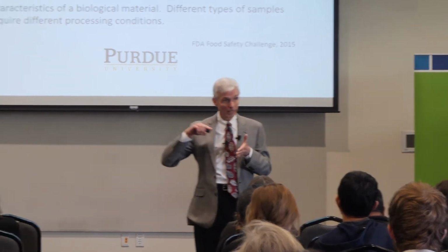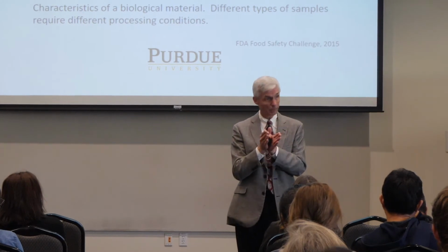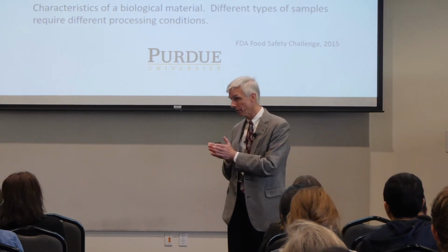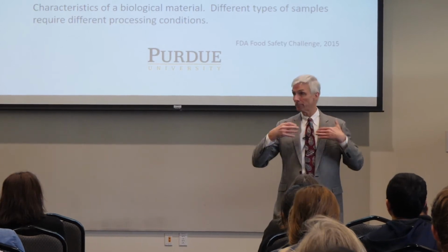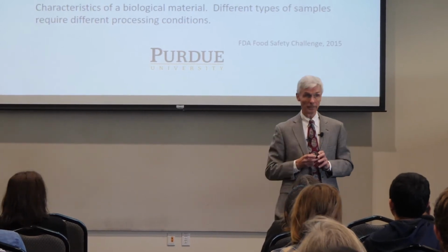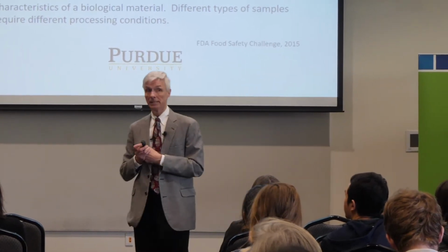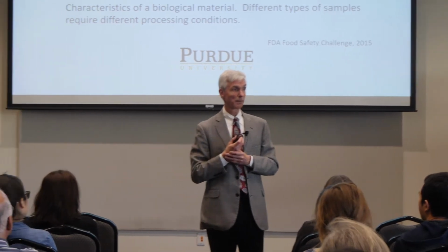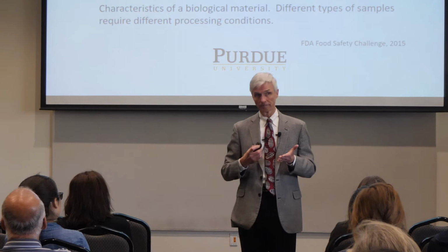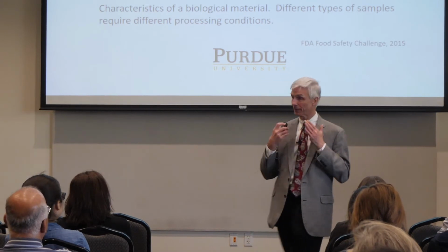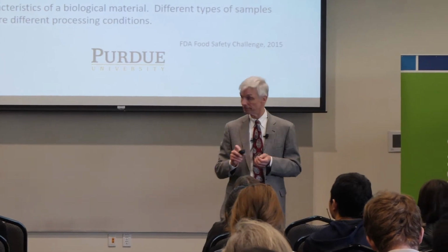So you'd think they would go right through the pores. They don't. They get into the pores, and then they start to interact with one another. And because the microenvironment is different, they will basically precipitate or aggregate and plug up the membrane. If you're working with milk, for example, it takes about 1 minute. The dead volume of these hollow fibers is very small, so if you pass 1 mil through, it's probably 20 or 30 dead volumes. That's enough to plug them up. And so what you have to do is find some way to prevent that.